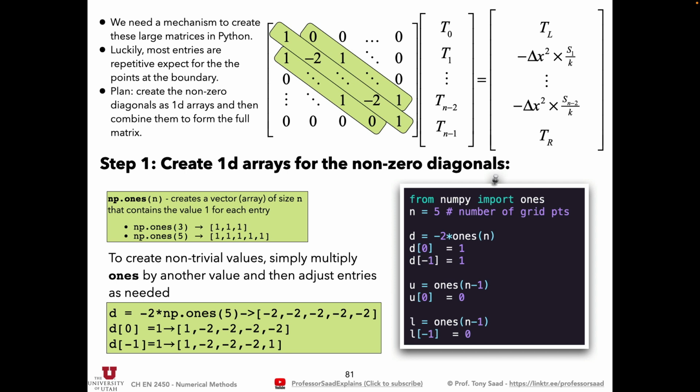If you recall, we were trying to solve this heat transfer problem in a rod. We took the continuous differential equation, discretized it, converted it into a system of algebraic equations, and put them in a matrix form that looks like this. The coefficient matrix has a neat structure. It's tridiagonal. The main diagonal is mostly the number -2. The first upper diagonal is all ones except the first entry. The first lower diagonal is all ones except the last entry.